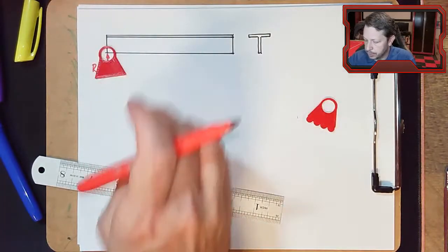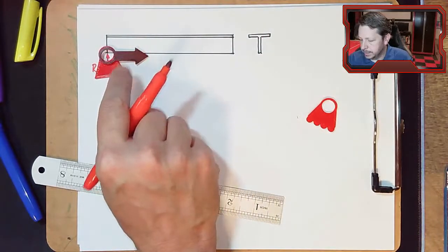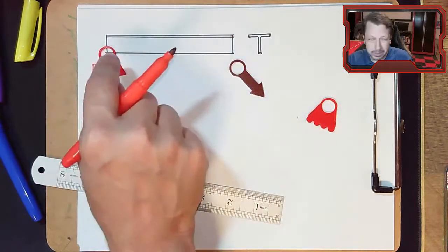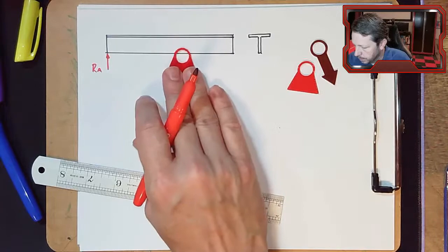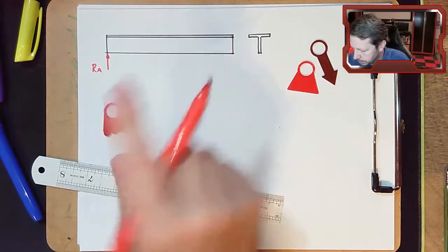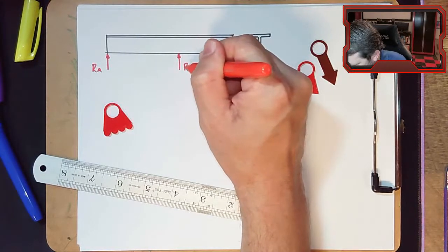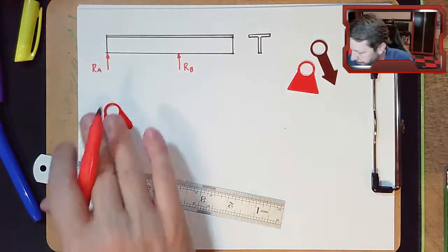There would also be a reaction in the X direction. But since there are no other forces in the X direction, we're going to say that this is 0. So you could draw it and zero it out. I'm just not going to draw it. Let's put our roller maybe somewhere in here. Normally we put them on the ends, but let's put it somewhere else just to have a different setup. That'll be the reaction at B. I'm just using A and B as two different points on the beam.